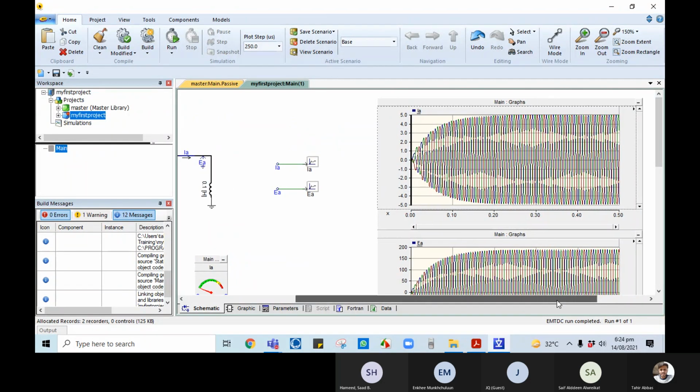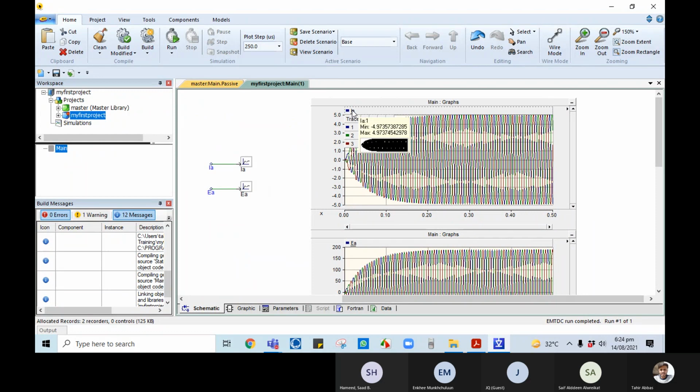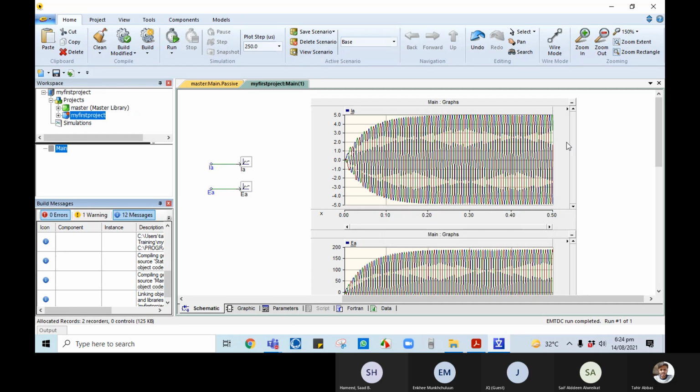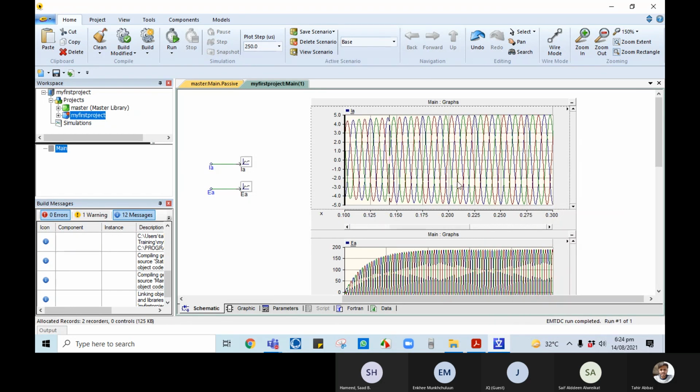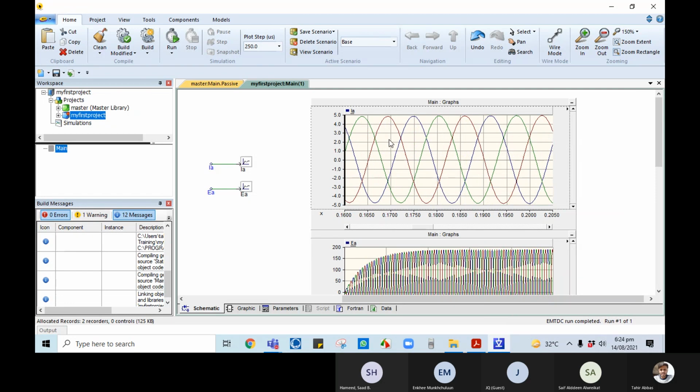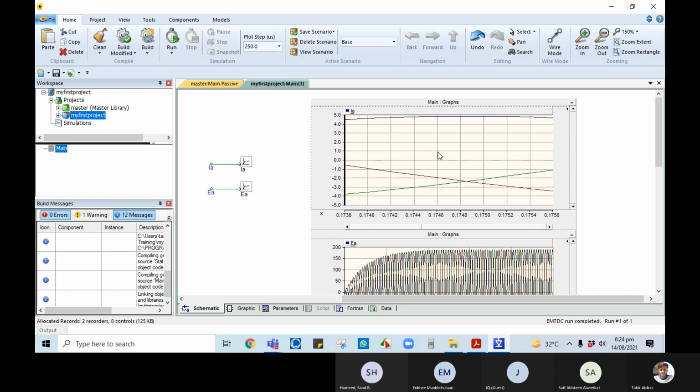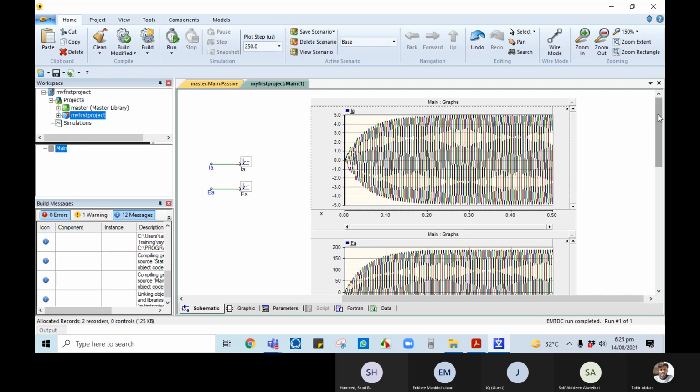In order to get more values, like here in IA, we can set different traces. The most important thing is that if we click on the x-axis, we can change the x-axis values here, and we can change the y-axis values here. So we can extend the range, and also we can press Control and left click to highlight a region. We can zoom into this one, or minimize it, and similarly here. If we press R again, it will come back within the range.